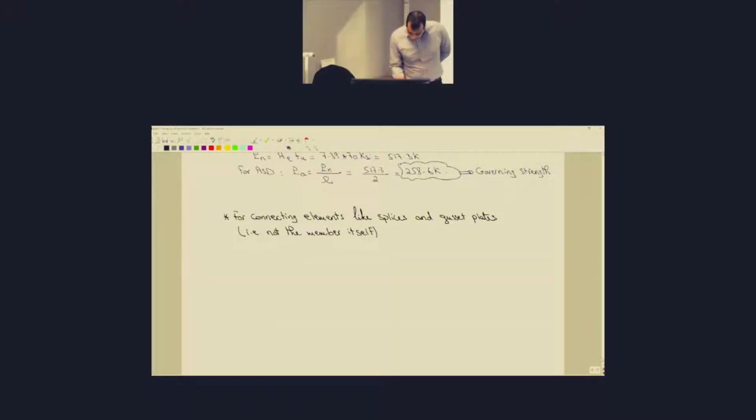So the AISC specifies that when you calculate the net area of this connecting plate, the net area cannot be larger than 0.85 of the gross area of the plate.